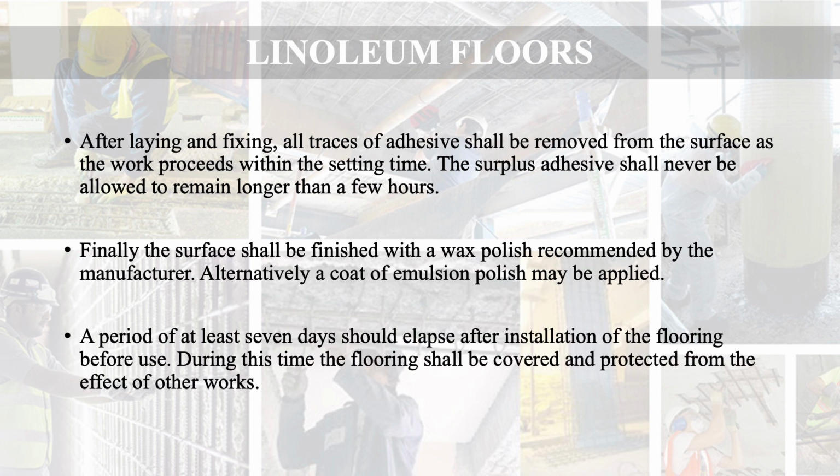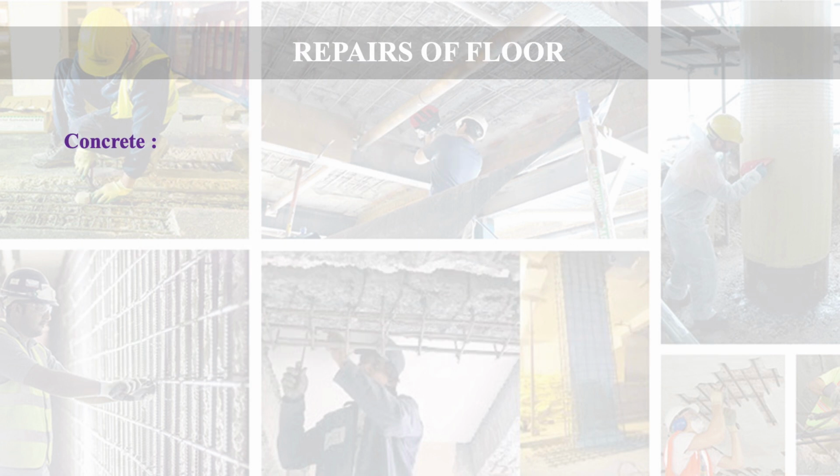A period of at least 7 days should elapse after installation of the flooring before use. During this time, the flooring shall be covered and protected from the effect of other works. Now let's move to the repairing of floors. Let's begin with concrete floor.